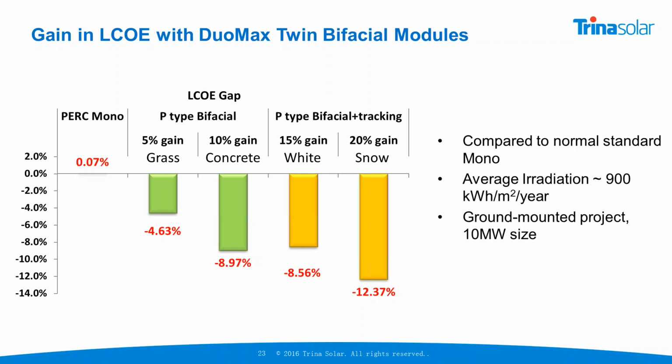Fortunately, the rear illumination is not as powerful as the front, and the mismatch between cells is not significant. So you don't have much mismatch, and the risk of degradation of reliability of the module is not great. We tested all of that, yes. We tested that in the laboratory, we tested that in the field, and we have not seen any additional reliability issue with this factor.